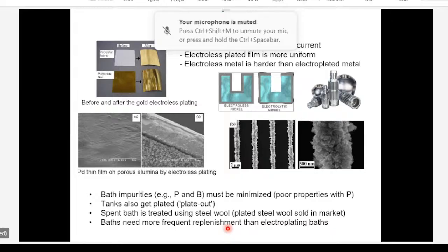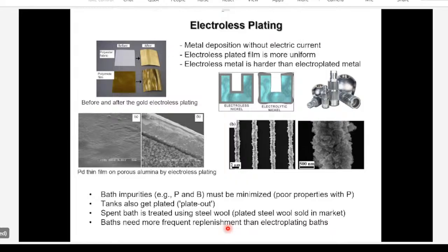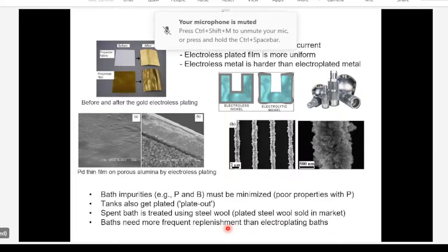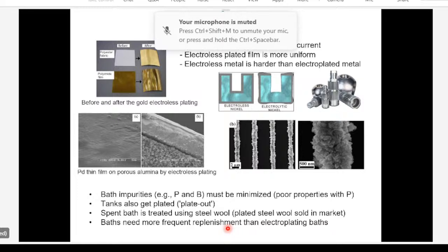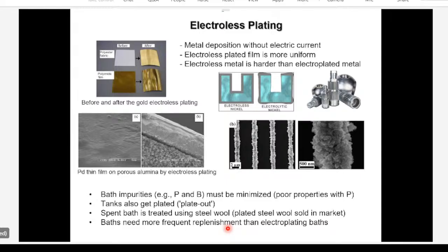They have changed some chains, the silver watch chains. Is it possible to do electrolysis plating on a silver chain? Yes, it is possible, but my understanding is that electrolysis plating does not give you very smooth or uniform deposition. So if they are using it for a wristwatch, I'm sure they are polishing or doing something afterwards to get a really good smooth finish. As-deposited electrolysis films are not very uniform or smooth. Are you saying that they use electrolysis plating on this chain here?